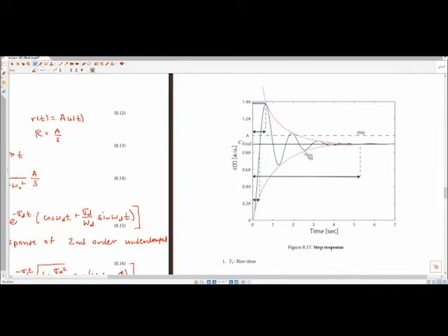so this gets back to the whole discussion of what open loop control would be versus feedback control. So here's our standard feedback controller, right? If we didn't have feedback control, that means that we cut this line here, right? And you could just put in, okay, I want to go a distance of 1 meter. You could have a general idea, and that's actually what project part 2 is asking you to do, of how much input into your system is required to move a certain distance. Part of the difficulty of that is you have to know your spring constants very, very well. And if you don't know that perfectly, you're going to be off.